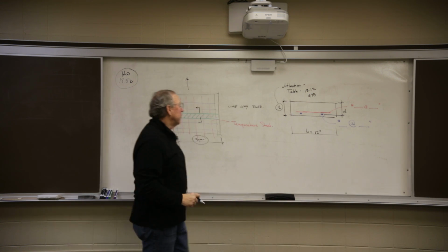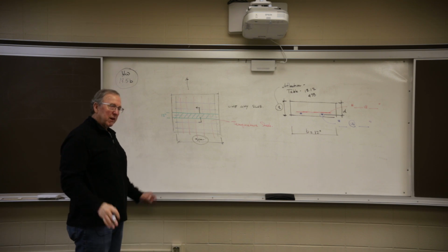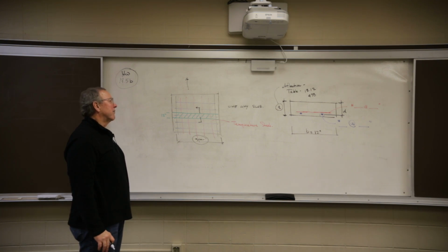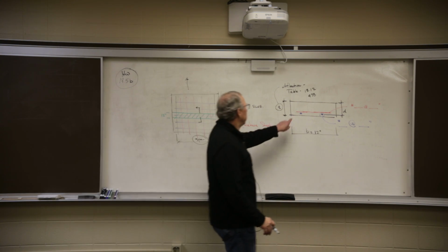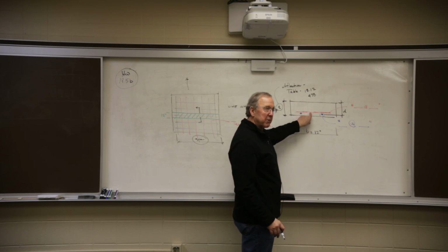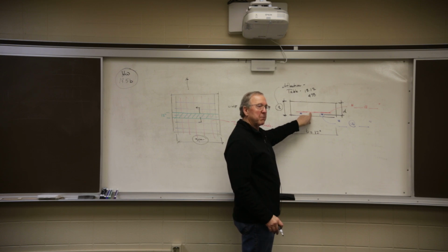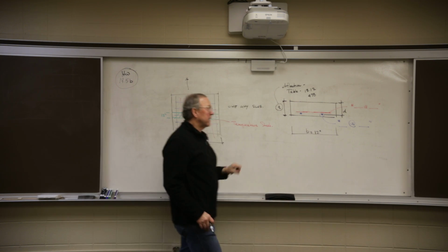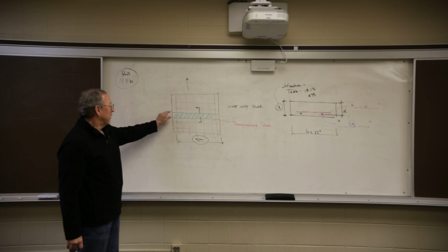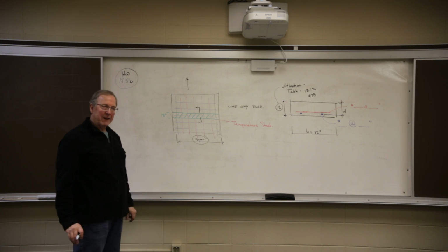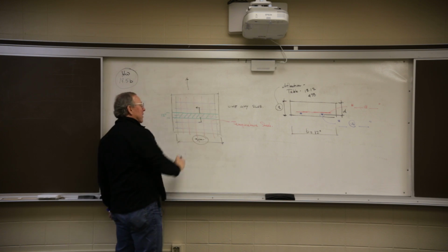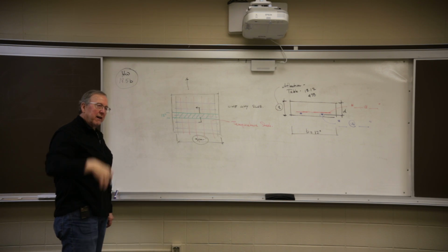So that's going to be our initial, find T. We're going to check it, make sure everything works. If it works, then we're going to determine how much steel we need for bending. That's this guy. And the next thing we're going to do is determine how much steel we need for shrinkage or temperature. And that's a code-driven percentage. That's a simple one. It will determine that. So remember, 1 foot width. The width goes across the short dimension, the span. The length is not relevant. Once it hits over twice the width, it can go on forever.